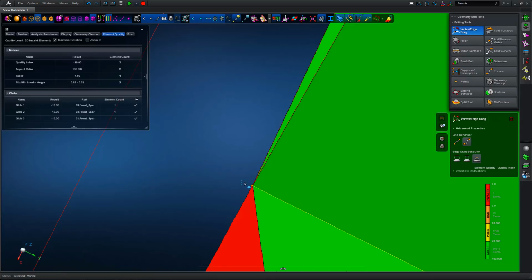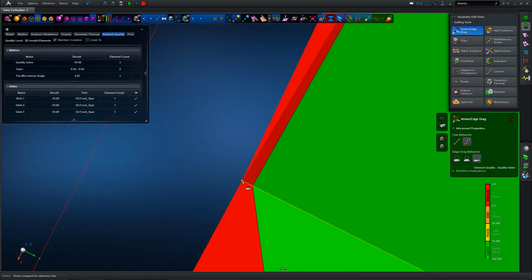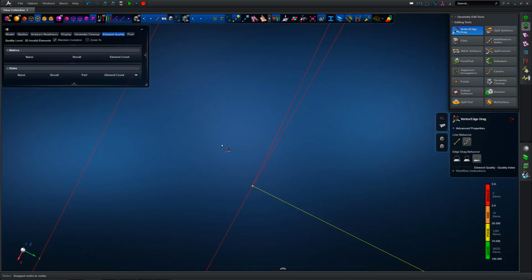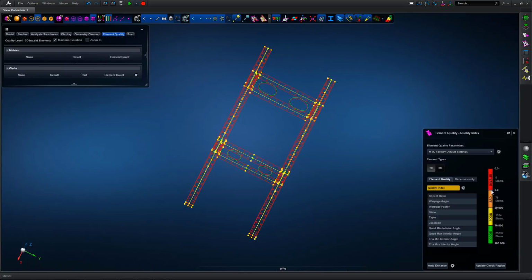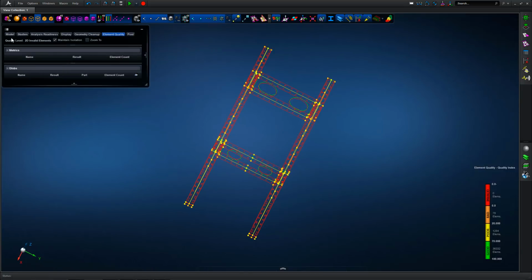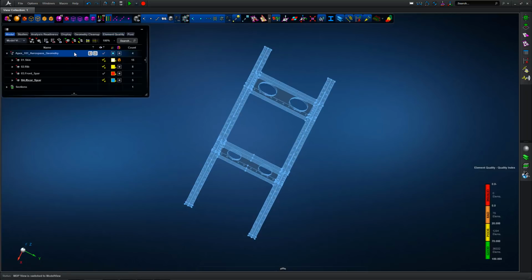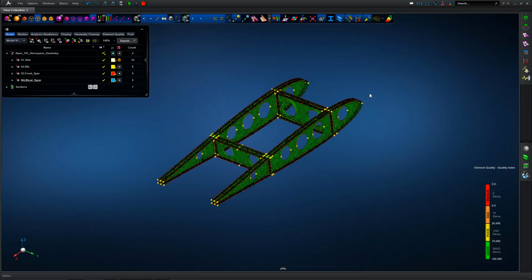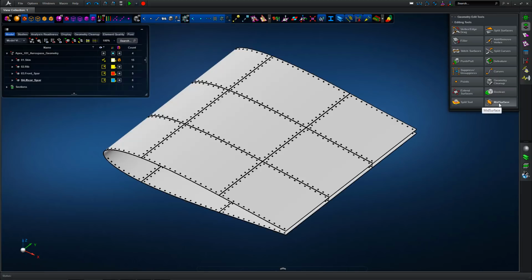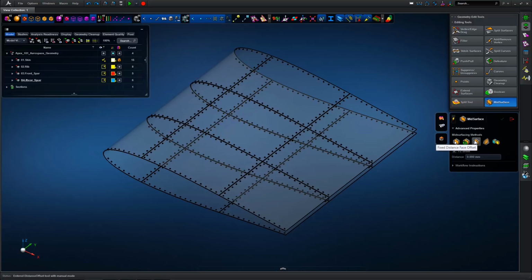And again here it looks like we've got a quad with a very small edge length, so simply moving one of the vertices out of the way, then snapping it back into the T-section, and the element quality is updated, and we have no invalid elements left in the model whatsoever. A very small number of bad elements, but massively dominated by good quality elements as a percentage of the overall definition. And bearing in mind that the element quality around fastener holes is controlled by the washer that we set in the feature mesh settings.